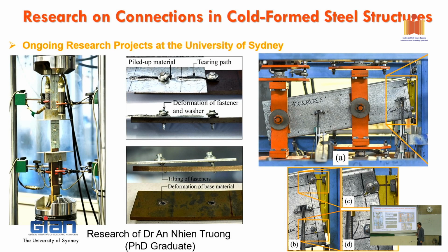Yes? Is the load applied through the CG or through the top? This one. What we do, you can see, we transfer the load from here to the thicker plate, and from the thicker plate to the big bar in here, and that bar pushes the screw. Is it only applied at the CG of the section? Yes, the C section, but we just transfer the load to the center of the web. We don't push on the top in here. Okay.